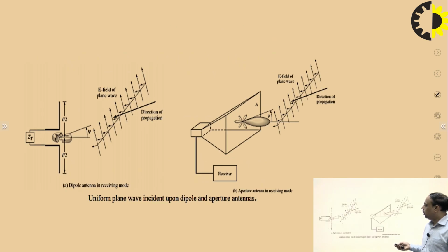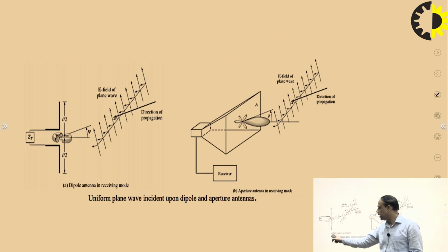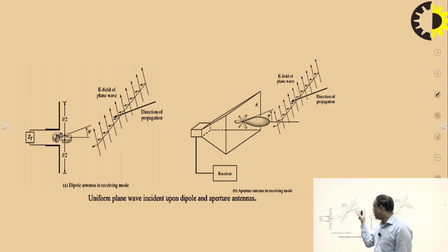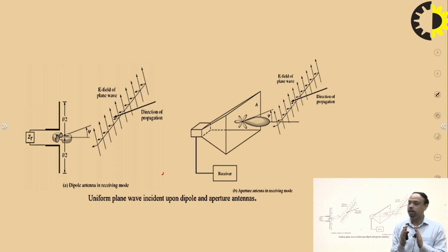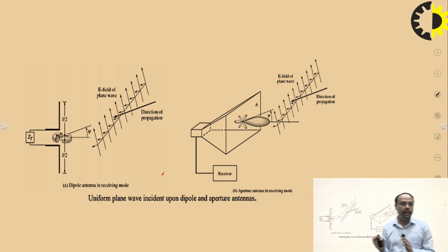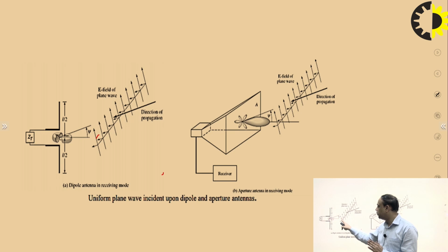Now if we consider an antenna lying in this arrangement, and this is a dipole antenna, and the electric field vector is tilted a little, the amount of the actual electric field received by this single polarized antenna, that is a linearly polarized antenna, is the intersection of this vector, which may be a very small amount compared to the total height of the vector.